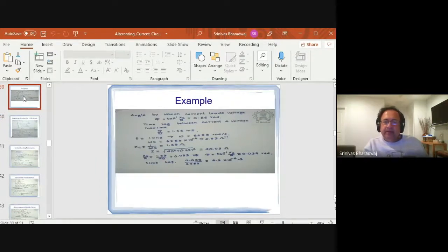As we indicated, the phase angle phi is obtained by taking the tan inverse of the impedance ratio, which involves the difference between XC and XL. So you take XC minus XL divided by R. The imaginary component is XC minus XL, the real component is R. So take the tan inverse of XC minus XL by R, and that will give you the phase, right?